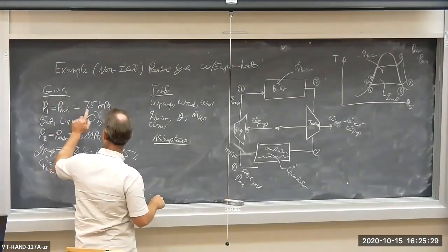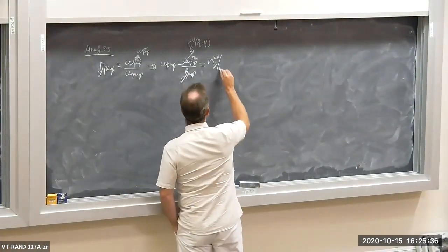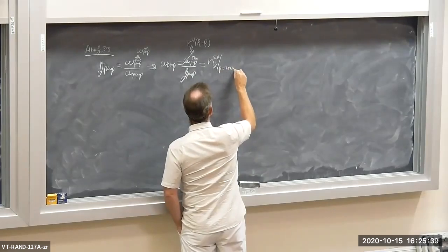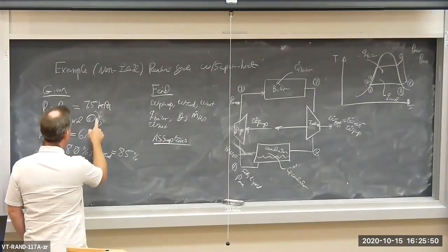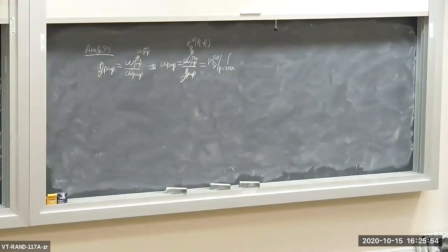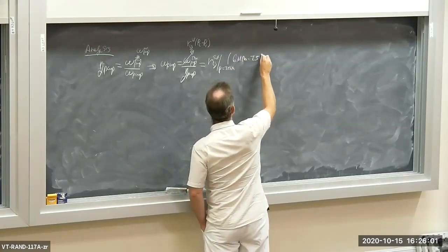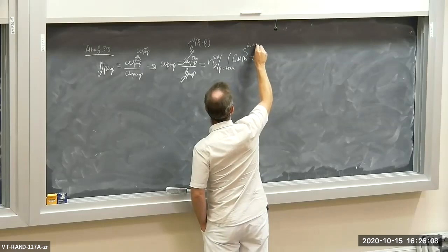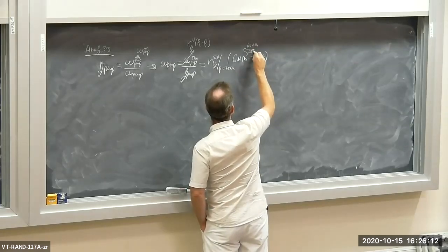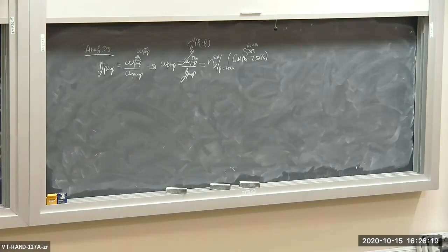So pressure P1 is 7.5 kilopascals. And then I have a delta P. Let's see, P2 again is 6 megapascals. And P1 is 7.5 kilopascals. 6 megapascals minus 7.5 kilopascals. So obviously I've got to do a unit change there. There are 1,000 kilopascals per 1 megapascal. So 6,000 minus 7.5 kilopascals.